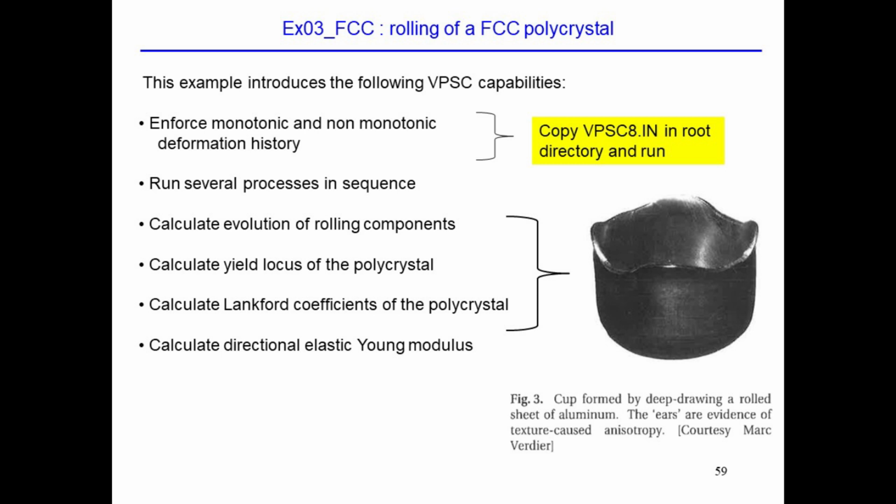So the way to do that is to tailor the texture and get textures that are as isotropic in the plane of the rolled sheet as possible. So that is one way. With alloying properly, you optimize the ductility of the product, so it is not going to break. The Lankford coefficient in particular will give us a measure of how bad this process is. I'm going to define it. So how bad this earring process is, that gives you an idea. And we'll move to the next one.